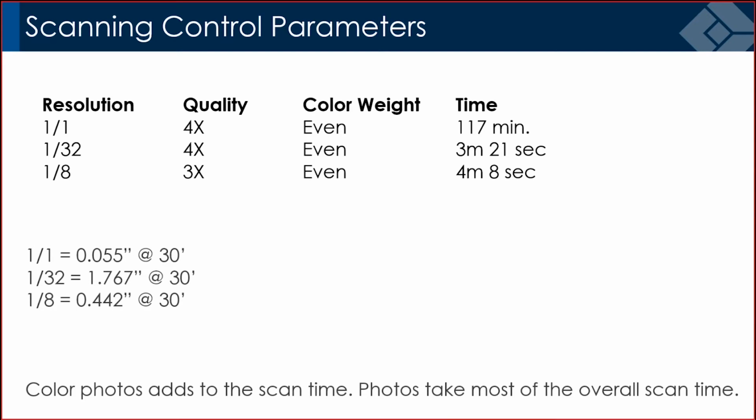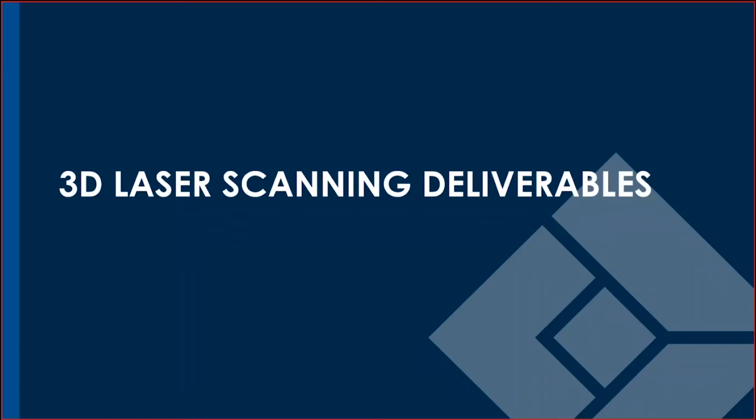What those photos do is help colorize the point cloud. If we don't take photos, you're going to get a black and white point cloud. So the question is understanding what's overkill and what's just enough, but that goes back to understanding what type of data we're going to receive and how we're going to model the data in the point cloud.